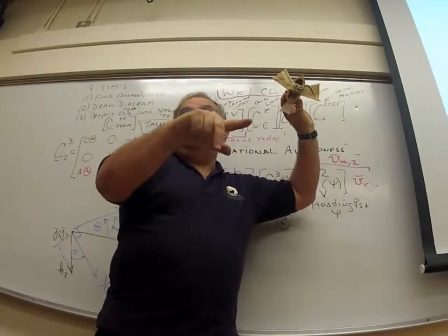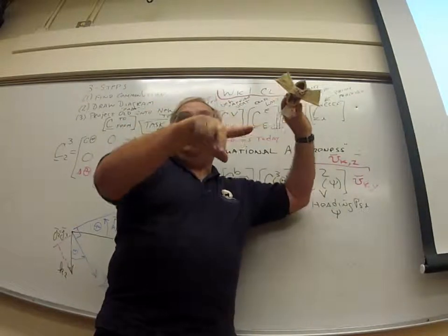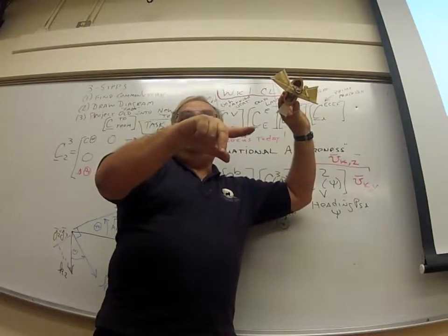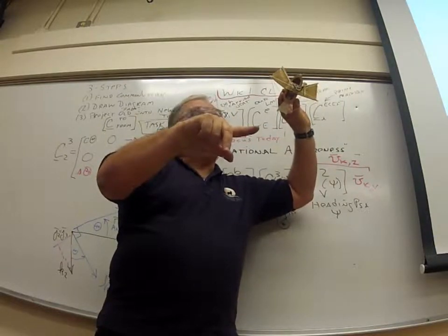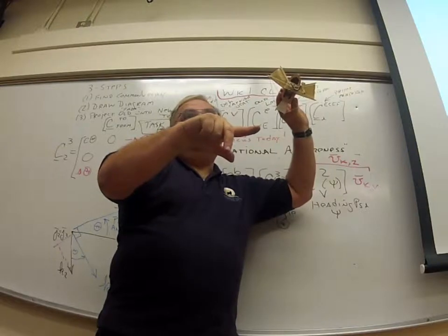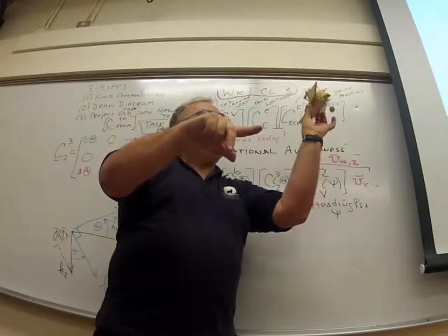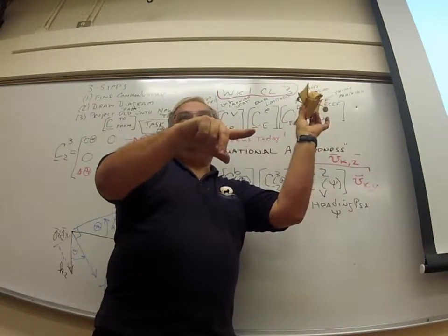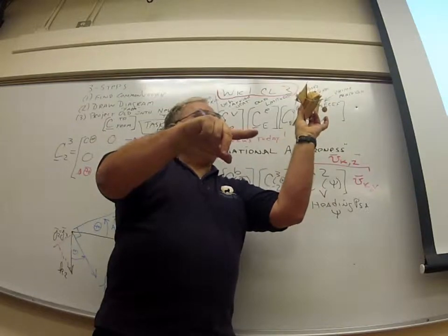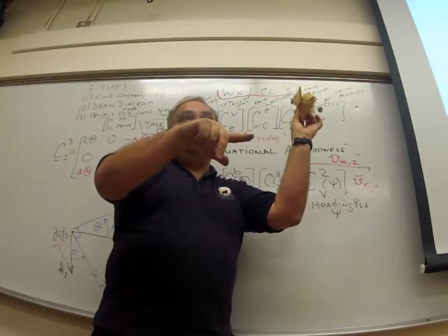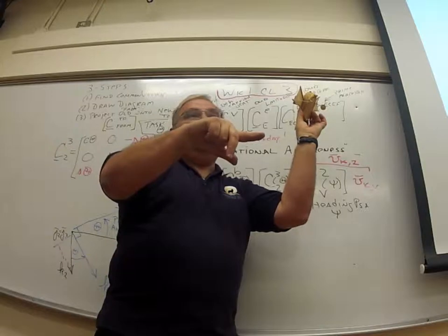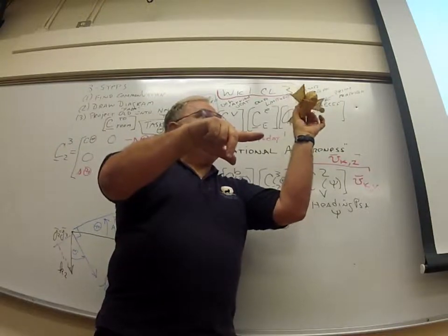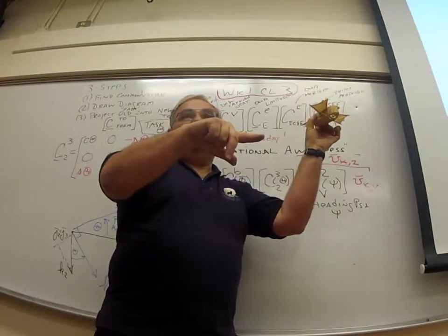So we have to go backwards now. If I want to go to northeast down from here, I got to go backwards. So I'm going to roll minus my roll angle about IB until my wings are parallel to the horizontal plane. Then I'm going to go through the minus J2 vector, through the pitch angle, minus theta, until my IB vector is in the horizontal plane.